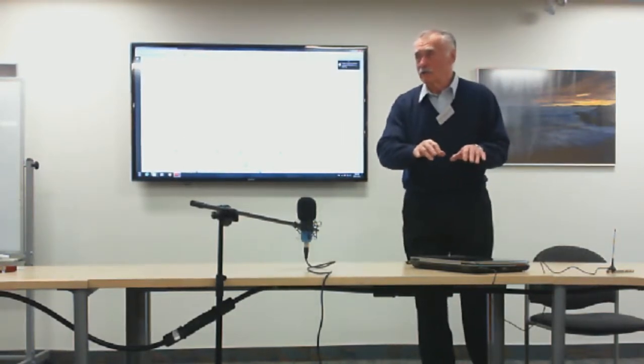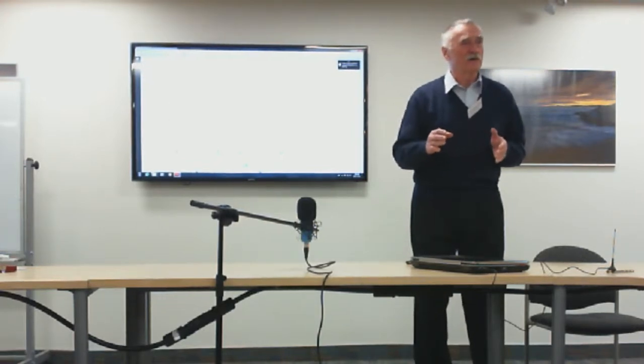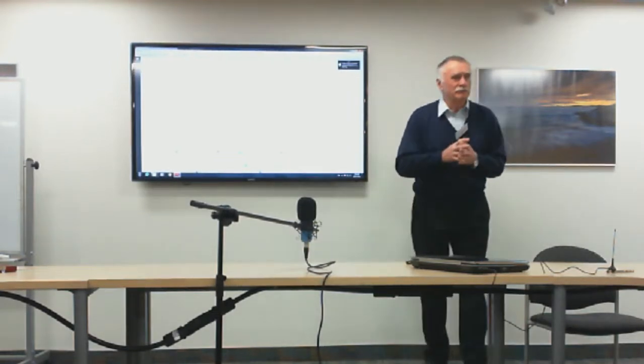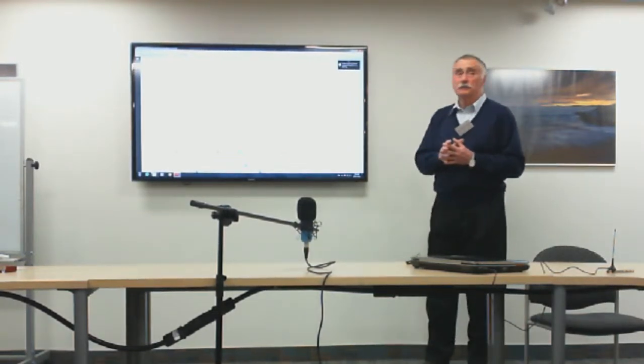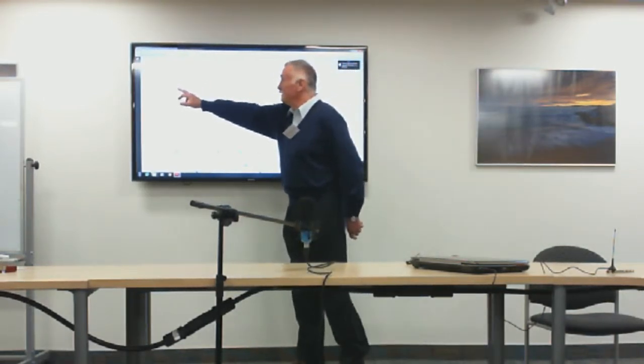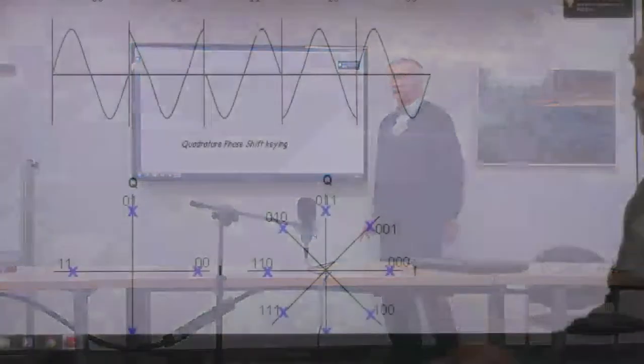coming, again, you type something on the keyboard. Whatever you type creates digital codes. Digital codes have bits. Those bits go to a terminal node controller, and the terminal node controller groups them, 2 or 3 or 4 or many, and each time 2 or 3 or 4 bits are grouped, there is a number of possibilities. For 2 bits, 2 to the second power is 4. Altogether there are 4 different possibilities, so the phase is being shifted 4 different ways.